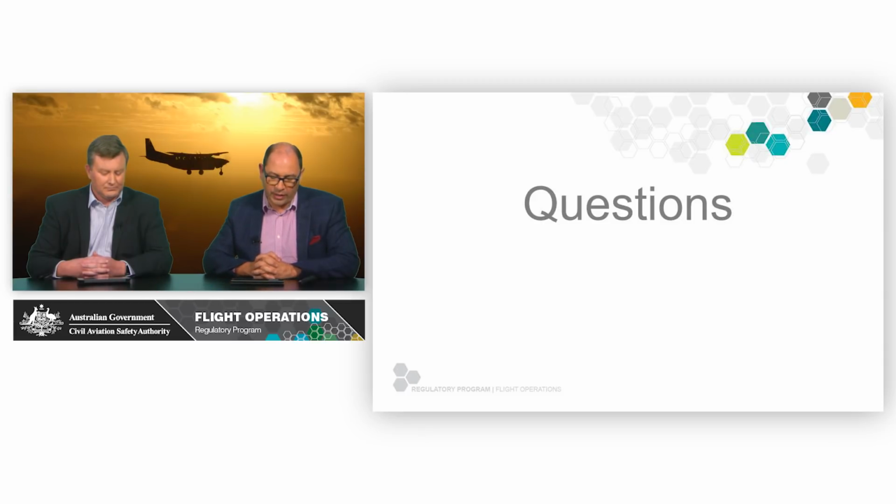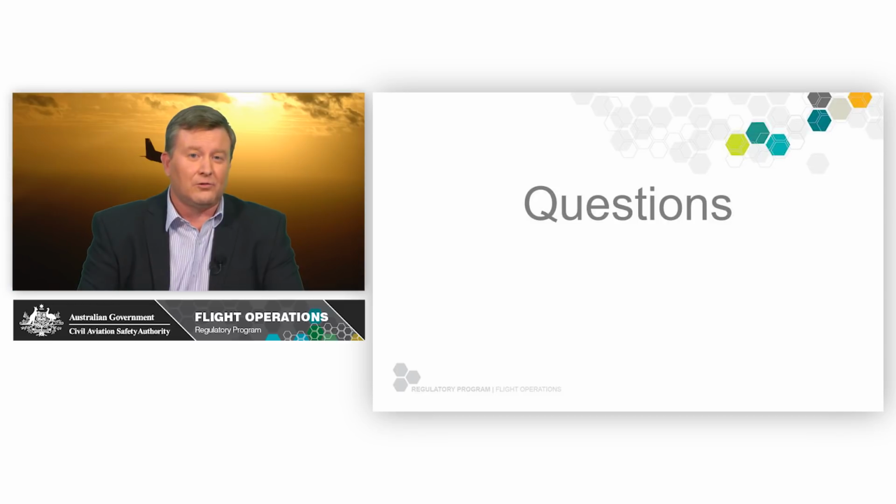So what's the weather radar requirement, and is this different from now? So, yeah, the weather radar requirement is almost identical. In essence, the only extension we've done to the weather radar requirement is if you're doing night VFR operations in addition to IFR operations, then you need to have weather radar. But that's obviously not for everyone. It's for the same type of aircraft that are currently required to carry weather radar. It's just that if you're doing night VFR ops in those aircraft, you also need it.